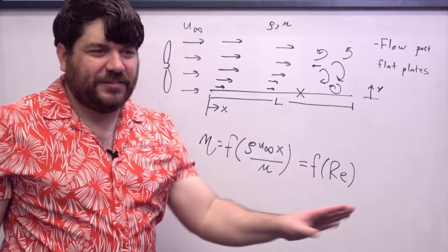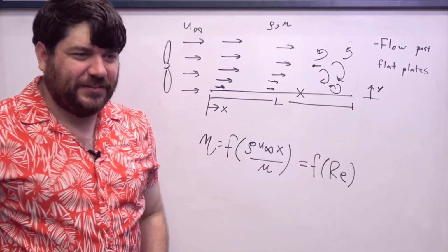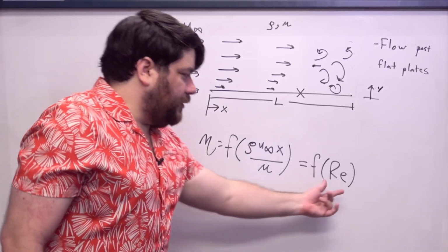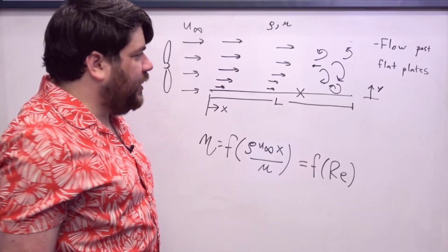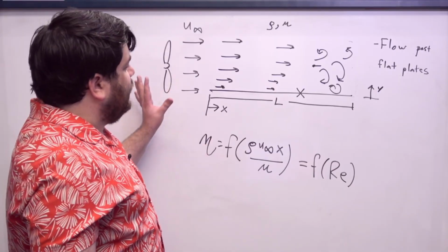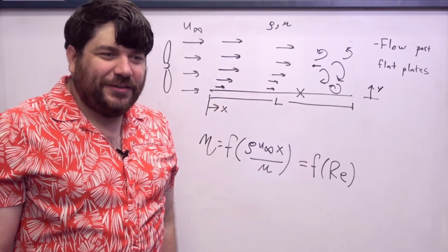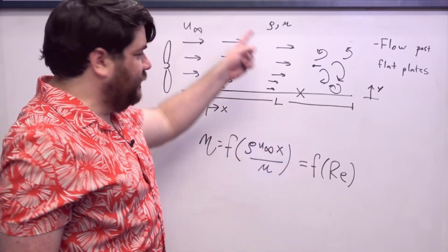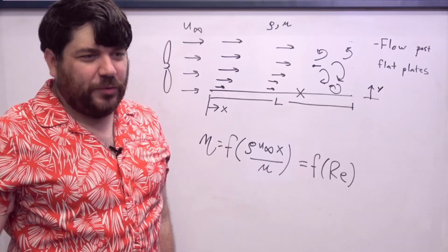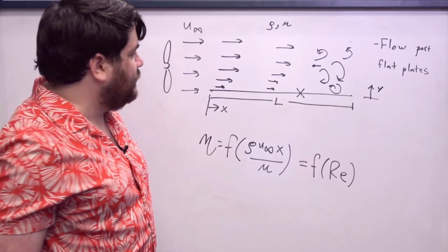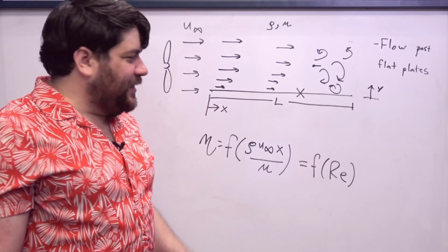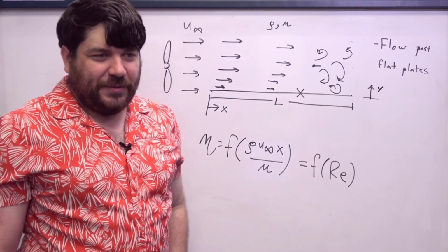That's a very easy way to mislead you into thinking that we know more about these systems than we actually do. The idea is to just think of the Reynolds number as being the only dimensionless parameter that will tell us what any other dimensionless output of an experiment will be a function of for a system like this, right? So we can imagine some other dimensionless output of an experiment that we perform on this system, and that output can only be a function of the Reynolds number.